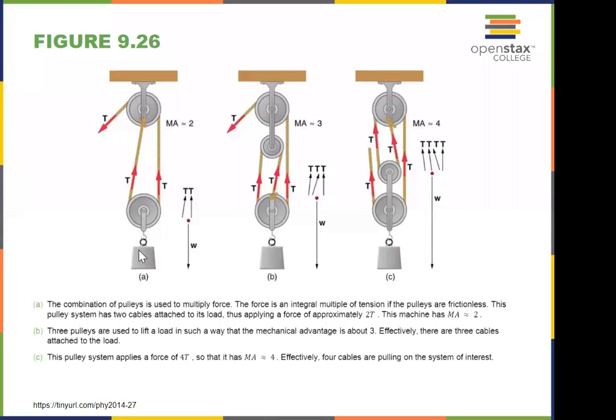So that means T is equal to half of the weight, or your mechanical advantage would be the output force, which is the weight, divided by T, which is equal to half of the weight. So then mechanical advantage here is equal to 2, roughly, okay? We say roughly because in a real scenario, there's probably light friction forces between the rope and the pulleys. I think we saw that in the Atwood Machines lab. So there's more friction force there.